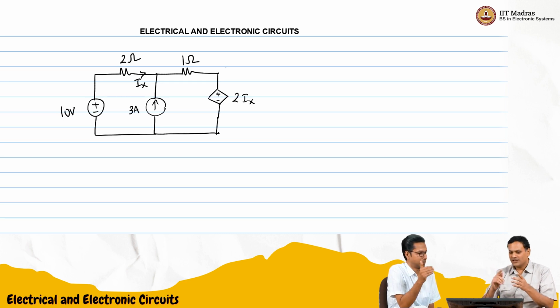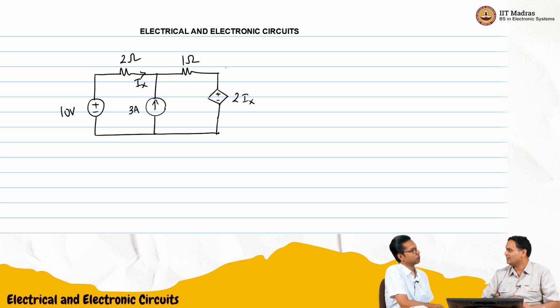Take the response, and what we would say is all other voltage sources are shorted, all other current sources are open. Those are for independent sources. But for the dependent one, we can't do that. We would just use it like any other resistance or inductance or capacitance in the network. We will just continue to have that dependent voltage source or dependent current source there in the network and solve it in each case.